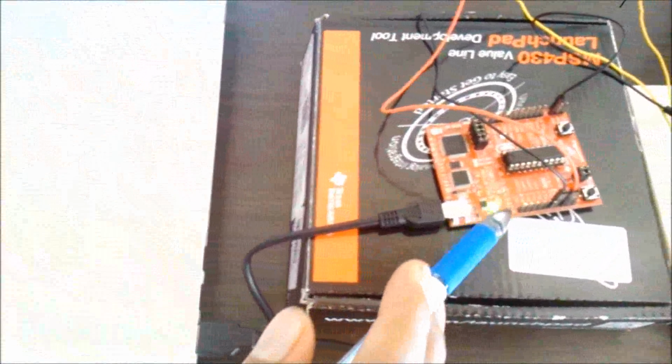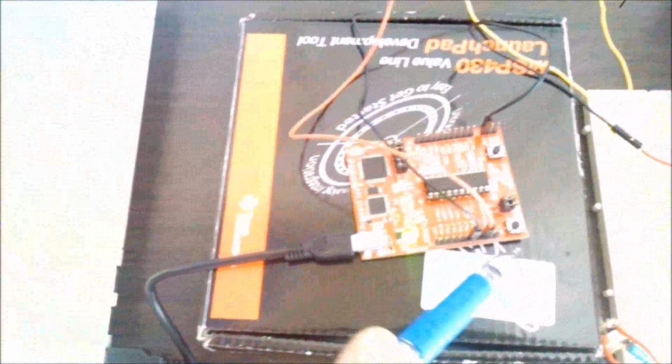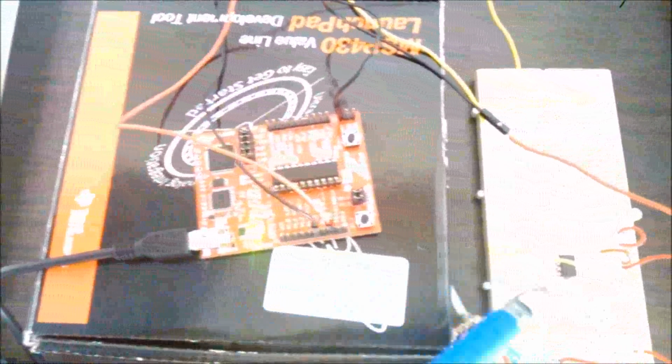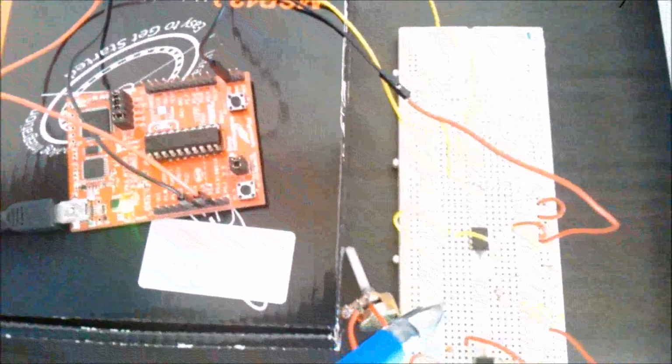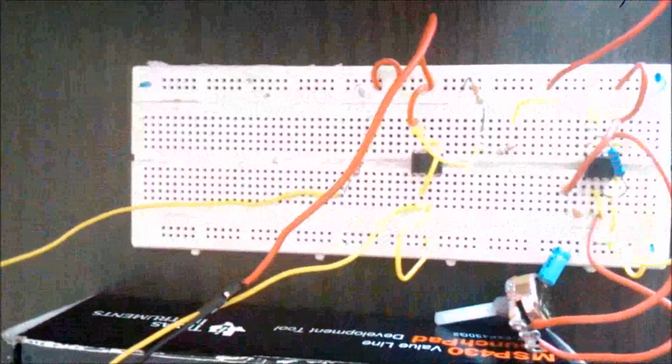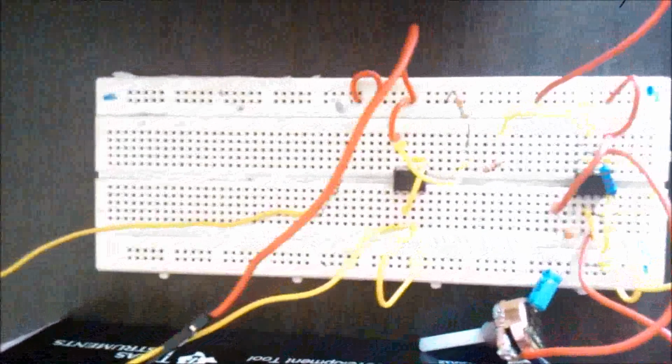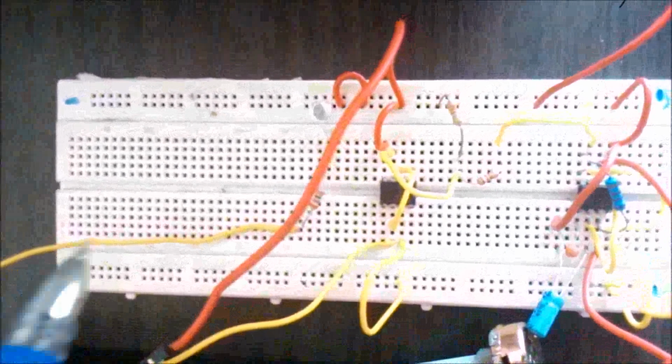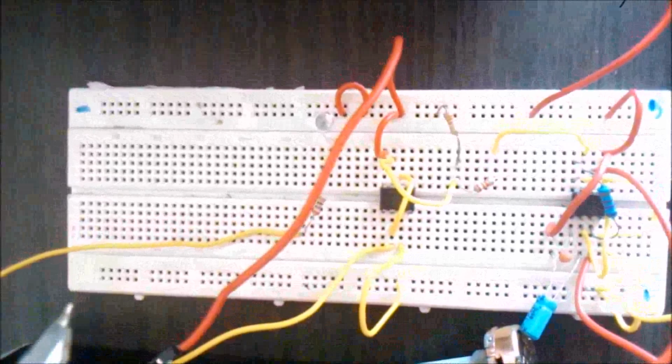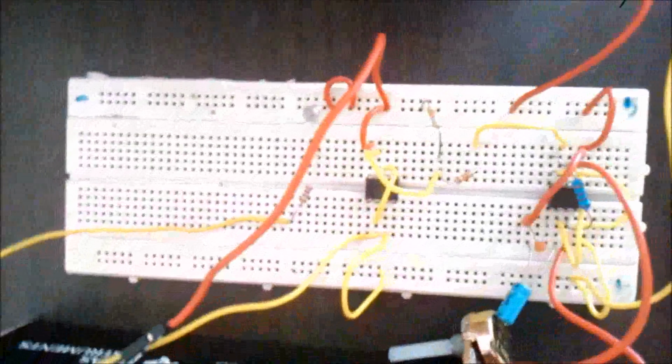Then the microcontroller is used to interface the velocity sensor. Once the pothole is detected, it measures the speed of the vehicle. This is achieved by continuously monitoring the output of the velocity sensor. The code written for the microcontroller counts the number of pulses and calculates the speed. Then the time delay required to activate the suspension is calculated based on the speed of the vehicle and the distance of the pothole from the vehicle. The LED is used as a suspension indicator which turns on after the calculated time delay.